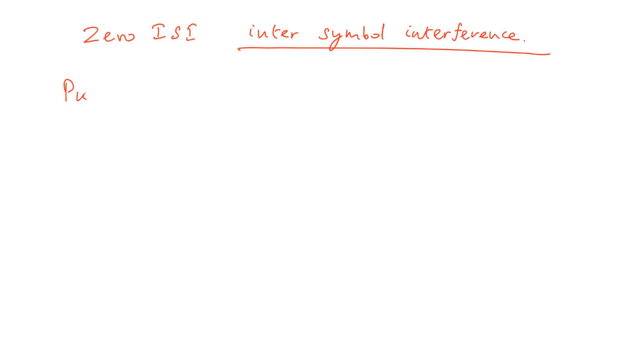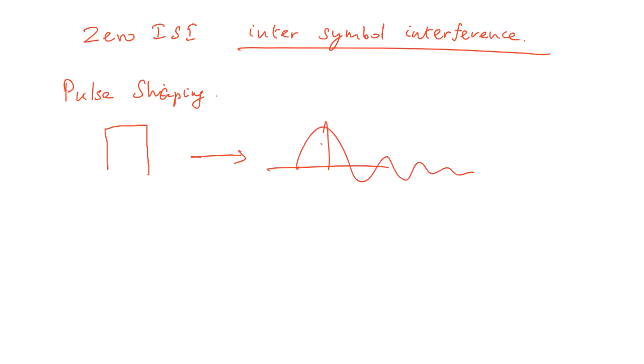Okay, you are not studying pulse shaping in this course. Pulse shaping is basically that we never transmit a rectangular pulse, because rectangular pulses require infinite bandwidth. I mentioned this at some point before the university closed. The rectangular pulse has a spectrum which is a sinc signal, that means it has infinite bandwidth, so we can't transmit a signal which has infinite bandwidth.